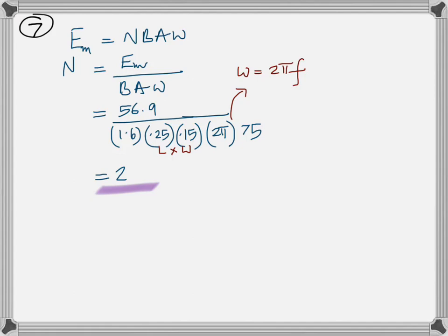You need to have a switch which has a high resistance at the beginning. And as the motor picks up speed, that resistance should go from high to low. Did you get me on that? Why? So as to limit the current at the beginning. That's such a real application that I wanted to bring it. That's why I put that question in there. Any motor, at the beginning, you should limit the current to it. Well, when it picks up speed, within a few seconds, it's okay. Back EMF is going to decrease the current through it.